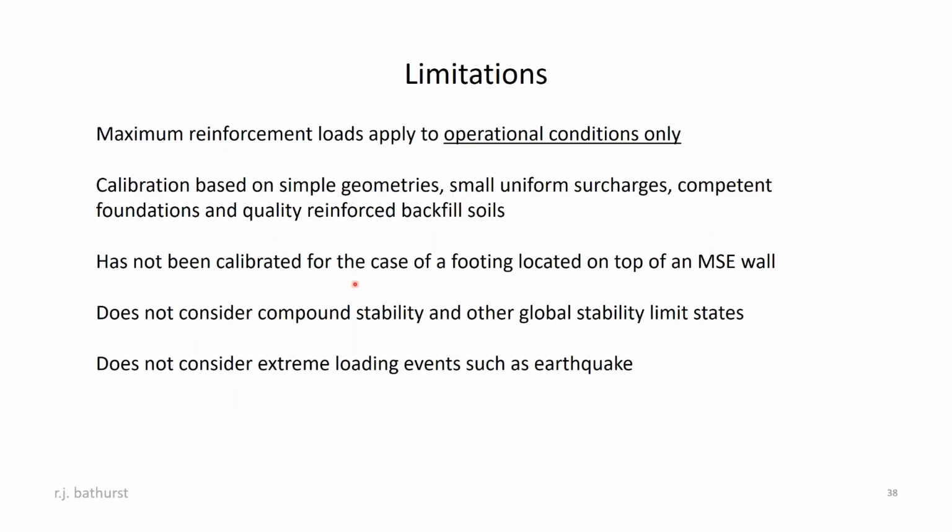We're still working on making adjustments to this empirical method for the case of footing loads on top of MSE walls. That work is still going on. It doesn't consider larger failure mechanisms like compound stability or other global stability limit states. And like I said, it doesn't include earthquakes.